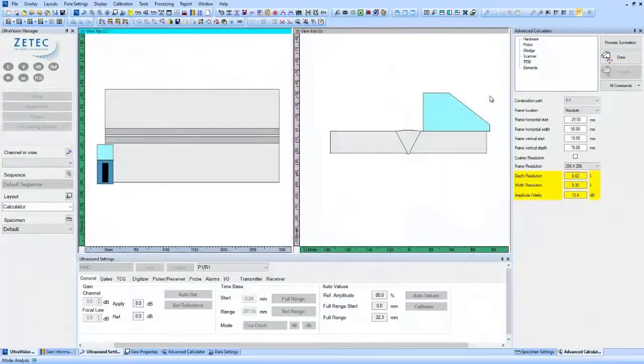The Topaz 64 also allows recording FMC data in full data mode. This means that a complete set of elementary A-scans is stored at each probe position in an encoded sequence. Ideally, this requires an automated scanning mechanism to control the movement. We will now process data from a carbon steel plate weld, where FMC frames were taken every millimeter, together with a live phased array channel.